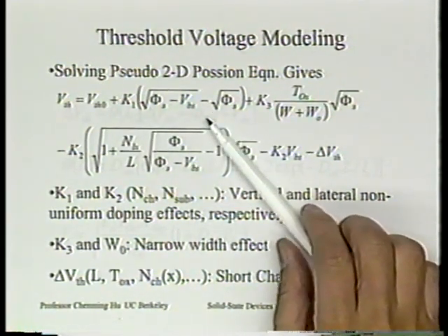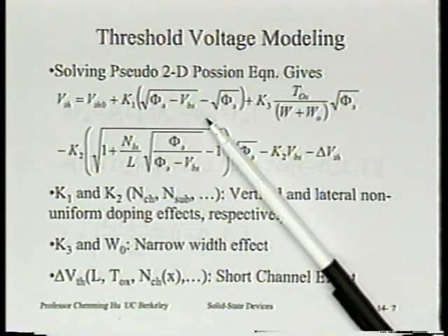And then, let's see, what do you think the first term is describing? What is it trying to do? What's that called? Body effect, right? Do you remember body effect has this? Now, using this way to describe body effect, what's the implicit assumption about doping concentration? Uniform. So do you actually think this is the very best way to model it? May not be, right? Okay?